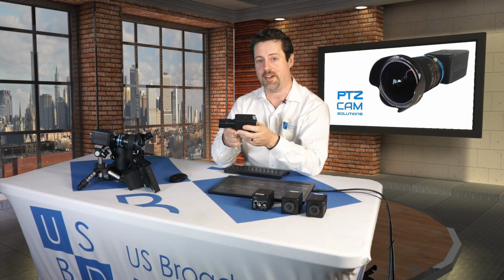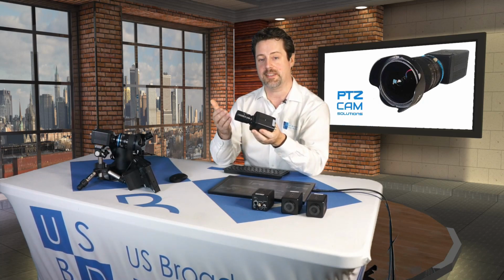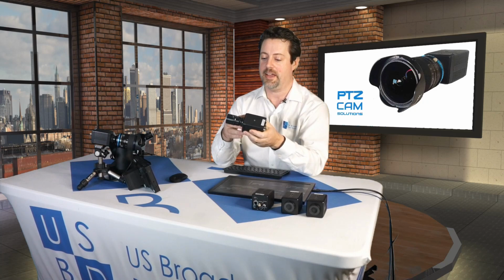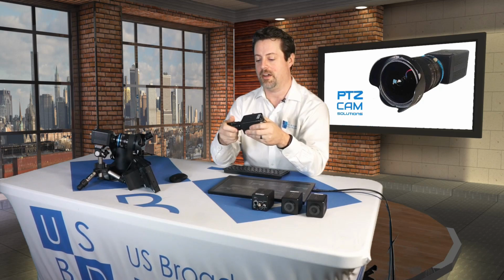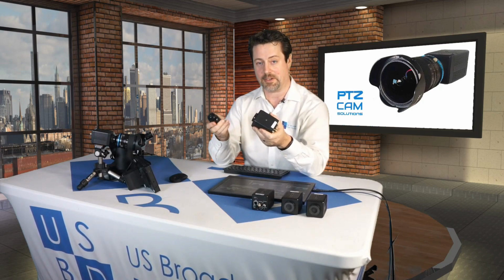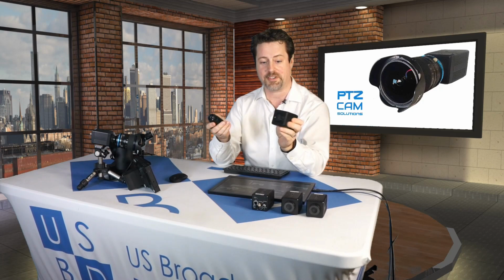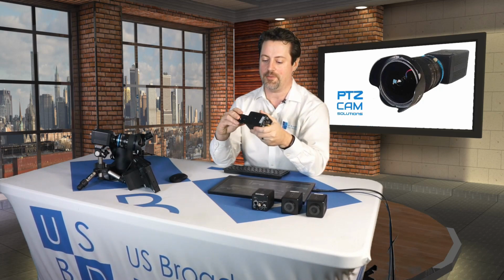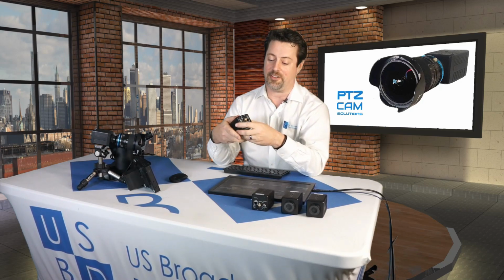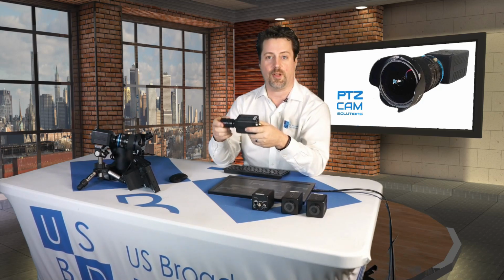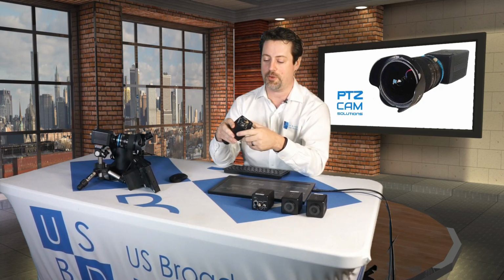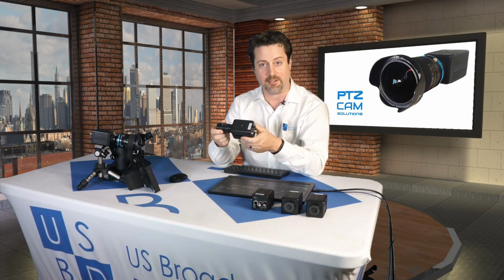It also has a half-inch sensor on it. So if you're into quality, this is full NDI, half-inch sensor, and it uses a CS mount lens system on it, which means that you can purchase a wide variety of lenses. As long as they're lenses that are compatible with half-inch sensors, you should be good to go. And there's a lot available in that category. On top of that, this unit also has 1080p 60 output via SDI. So the combination of full NDI, half-inch sensor, SDI output makes this a camera that you might want to take a look at. So let's take a look at it.